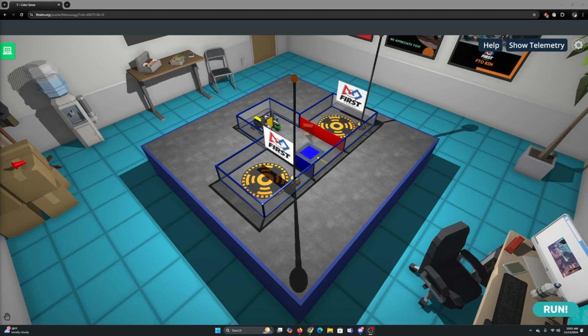To help us troubleshoot our code, we're also going to use something called telemetry. With telemetry blocks, we can display the color of the panels directly beneath the robot. First, we are going to code our robot to drive over the color panel. In this video, I'm just going to use time-based driving, but this should work with encoder-based driving as well. To shorten this video, I'm just going to pause, build my drive forward code, and then we'll resume at the end of that.